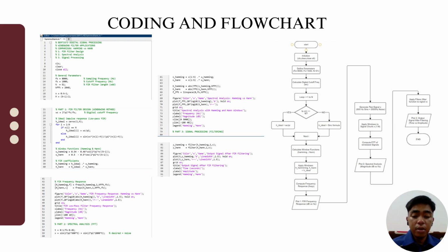After that, in the design of the FIR filter, we calculate the ideal impulse response. Theoretically, the impulse response of the ideal low pass filter is a sinc function.